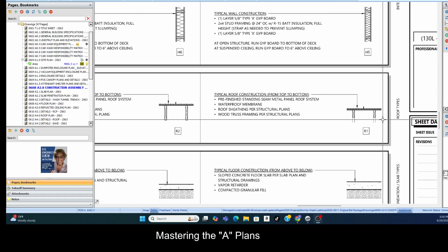Your framing will probably be higher than your drywall or whatever. So even if it's an assembly, you want to always accurately determine how many square feet of both. Your drywall may only go up to a certain point, or at some point it may be FRP.